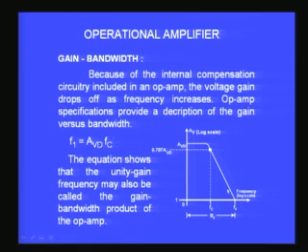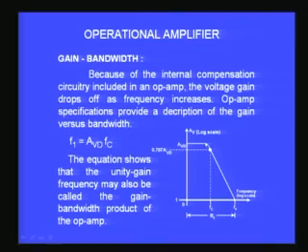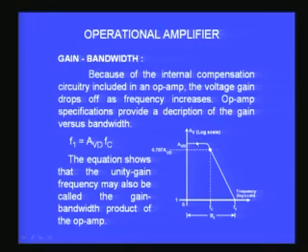And so this is a roll off, and if I want to measure bandwidth, the bandwidth is generally defined. Well, how do you define the cutoff frequency for knowing the bandwidth? I should know what is the cutoff frequency. The cutoff frequency is not the knee portion where it starts bending, it is actually the point where, if it is a voltage amplifier, the voltage gain becomes 0.707 times the mid frequency gain.